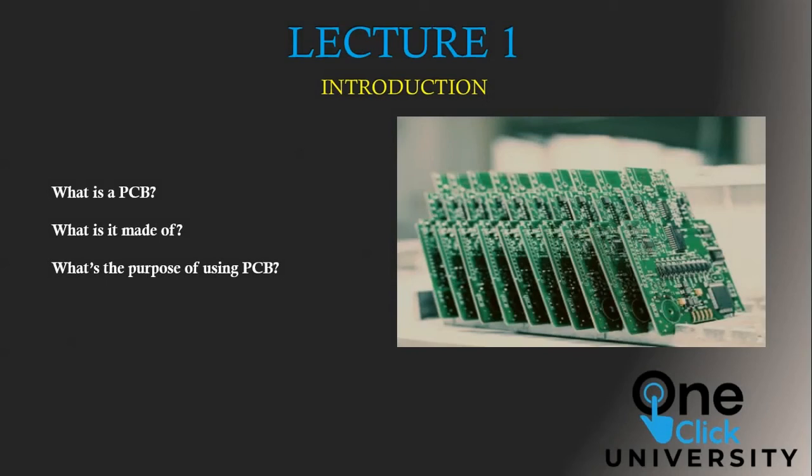A PCB is a thin board made of either fiberglass composite epoxy, commonly known as FR4, or any other laminate material. The board supports and electrically connects electrical or electronic components using conductive tracks and pads etched from sheet layers of copper laminated onto layers or between sheet layers of a non-conductive substrate.